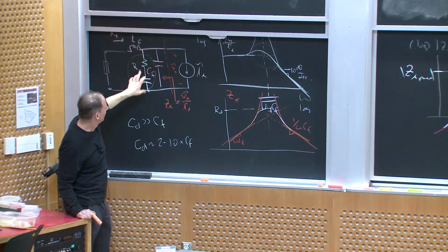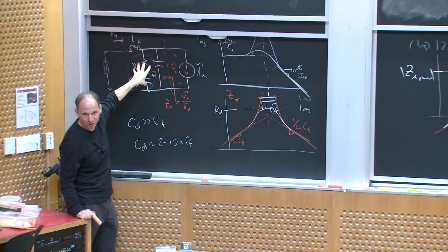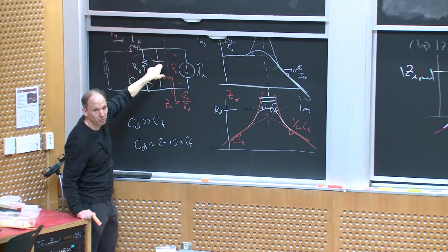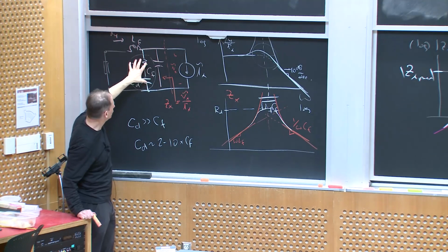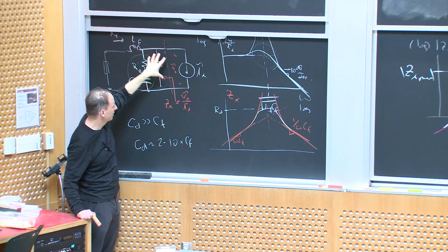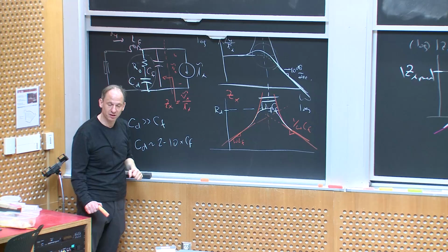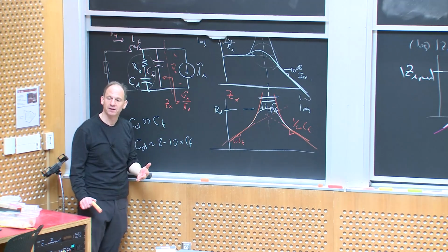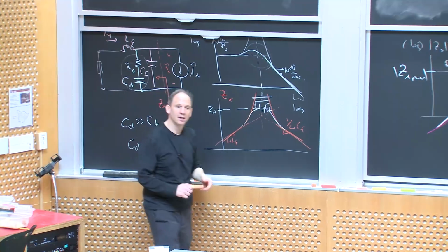So this might be, for example, an electrolytic capacitor, whereas this might be a film or ceramic capacitor. So the jobs of these two capacitors are different, and the construction of them. And you can get a lot of energy storage in electrolytic, for example, as compared to a ceramic or a film capacitor typically. Okay. Any questions about that?